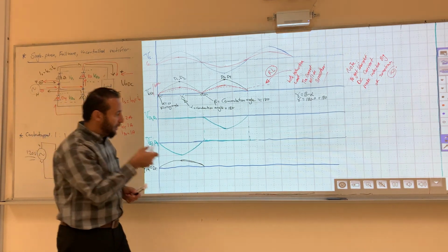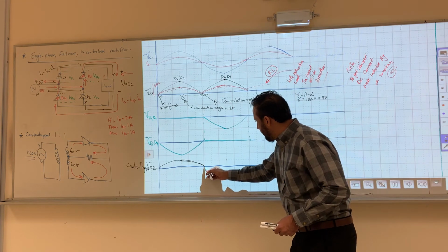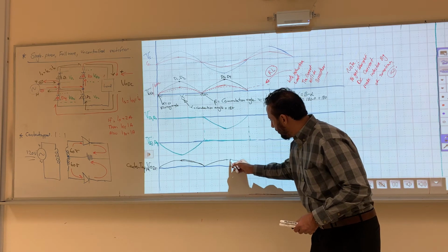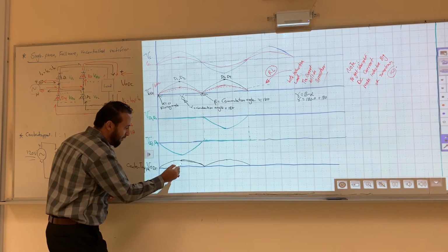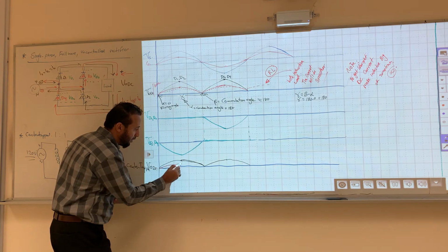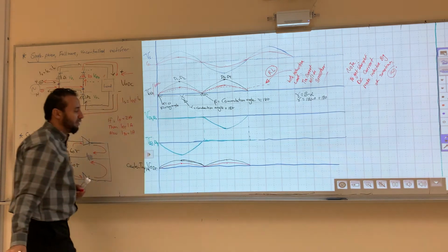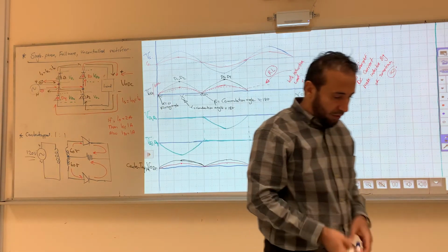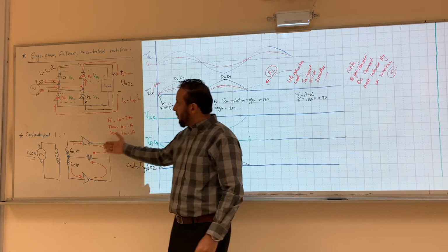And then the other pulse will be here, something like this, and something like this. That's the V out. The current will be half. Something like this. That's the center tab. So it will be the same, but the peak is half. If they ask you what's center tab, you can say it's like two half waves merged together. This is a half wave, and this is a half wave.